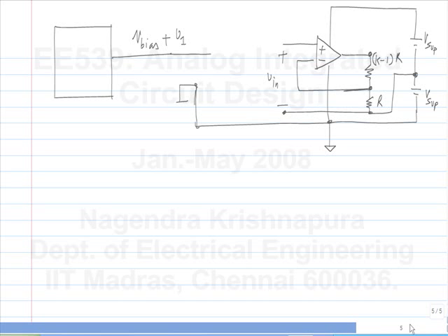What's that? To do what? No, but let's not change the circuit, right? Meaning I want the same signal processing functionality. How would I arrange things so that V1 appears at the input and it behaves more or less the same? No, I don't want to do that. I don't want to change the total supply to the op amp. What do I have to do? So I already said that the input bias doesn't have to be the midpoint of the supplies.